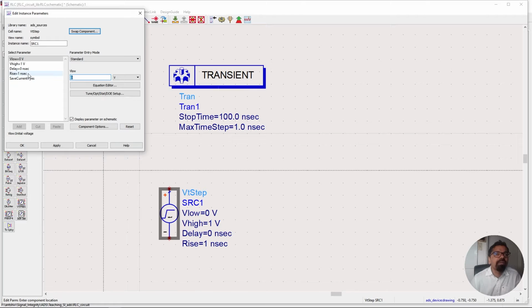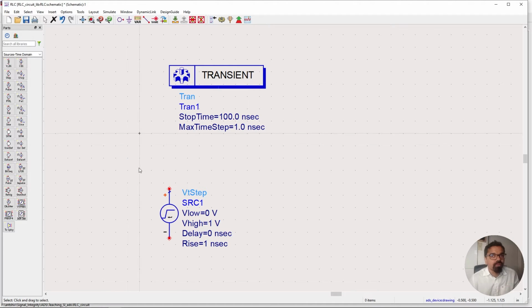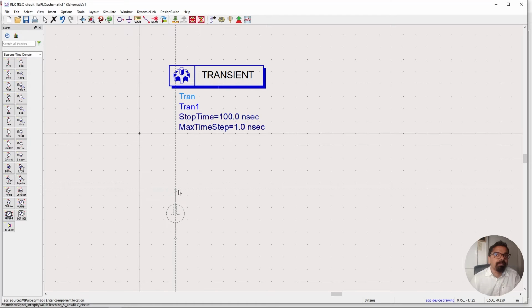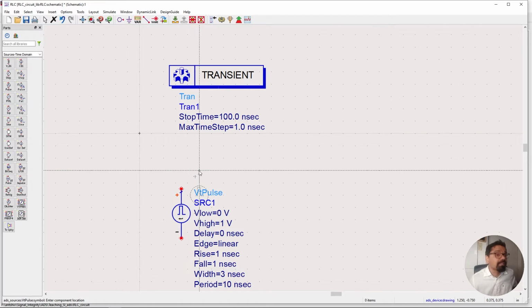Now, what this might do is it might give me a very smooth, almost instantaneous rise time. And maybe that's not what we want, because that's not how real circuits work. A real step response will have a rise, it won't be instantaneous. It would happen over, say, a nanosecond or a picosecond, but it will not be continuous. There'll be a time before it goes from 0 to 1.